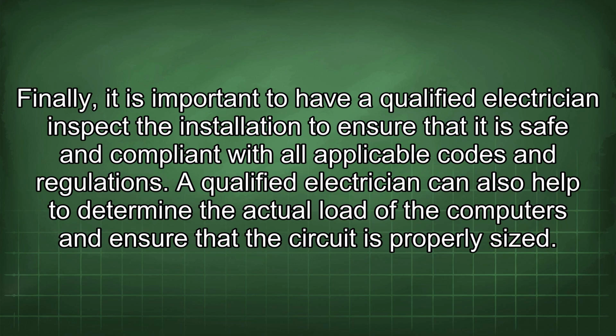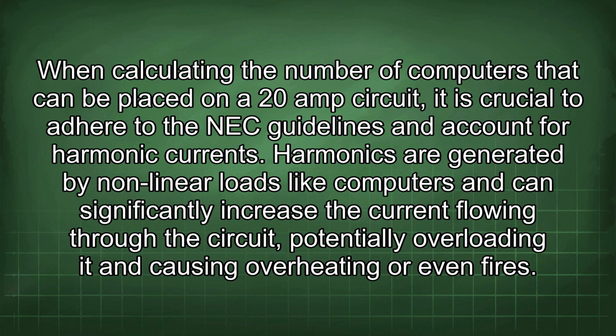Finally, it is important to have a qualified electrician inspect the installation to ensure that it is safe and compliant with all applicable codes and regulations. A qualified electrician can also help to determine the actual load of the computers and ensure that the circuit is properly sized. When calculating the number of computers that can be placed on a 20 amp circuit, it is crucial to adhere to the NEC guidelines and account for harmonic currents.